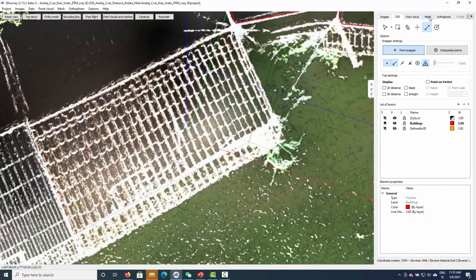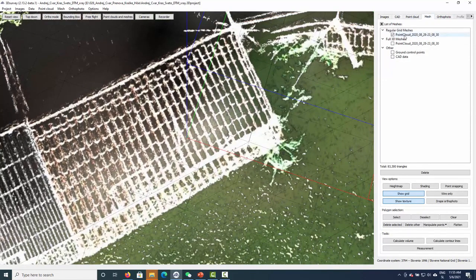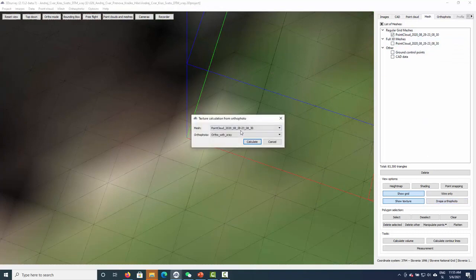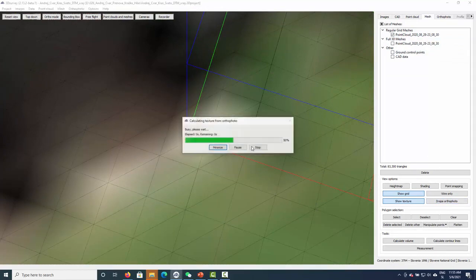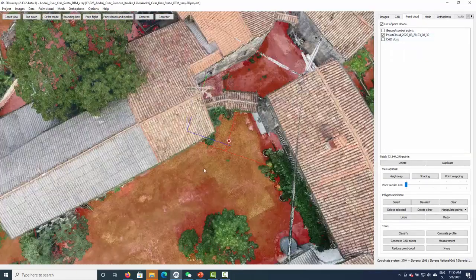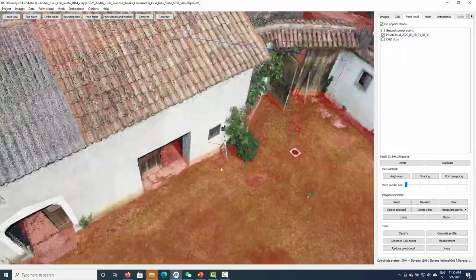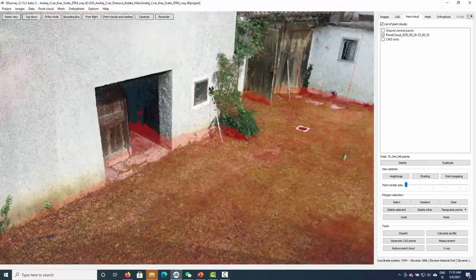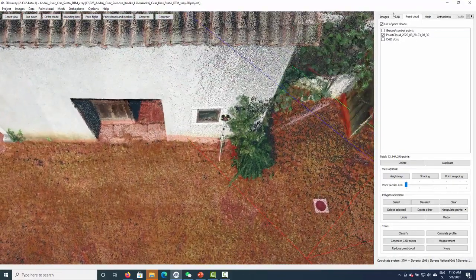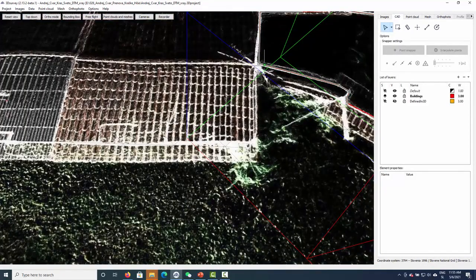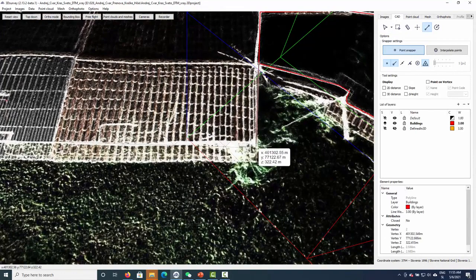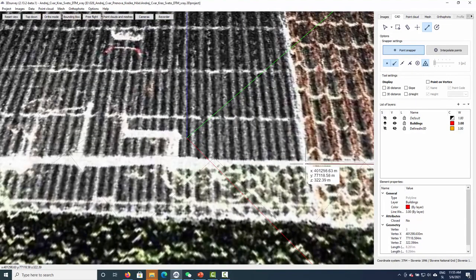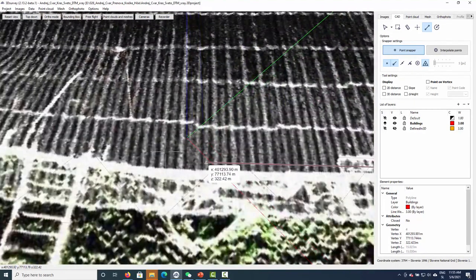Maybe now let's switch a little bit to another texture. Remove this one, drape ortho, the one with black background. Just for a second I'll turn the point cloud on. So yeah, here we see we have this kind of situation, so probably we should take the inner wall for the edge of the building. Turn it off. So like that. This should be the edge of this building.